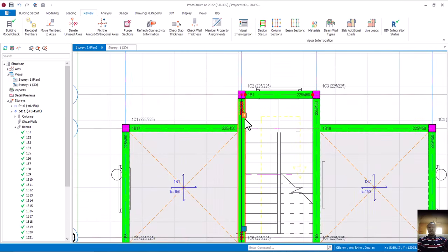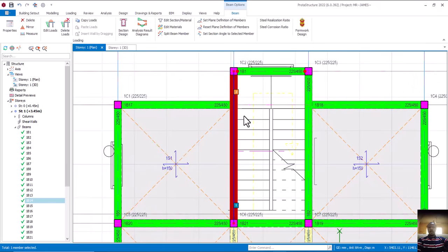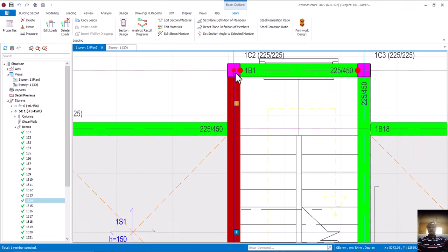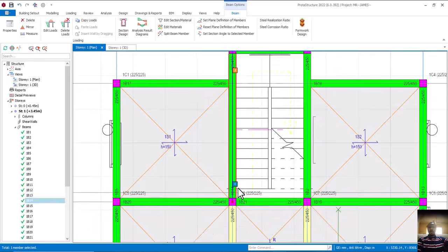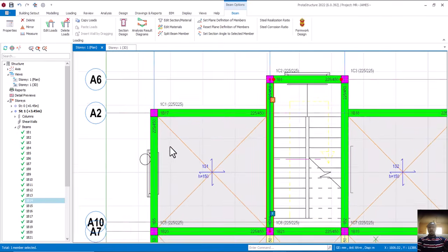If you also look at this primary beam, I always advise that anything that has to do with a primary beam, a major beam, don't hinge that place. That's my own advice. If not, if you have to go by condition, definitely you can hinge this place. This is condition. If you are to hinge this one now, we are going to hinge this particular beam at J, which is here, but at I we can't hinge it. So that is that.